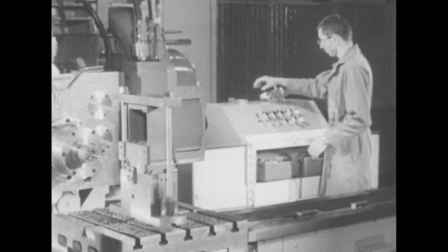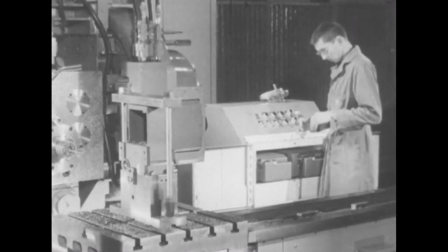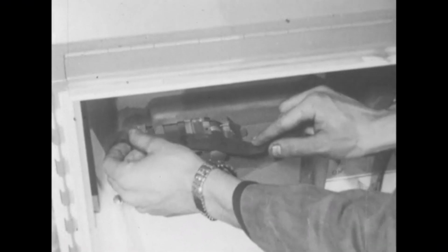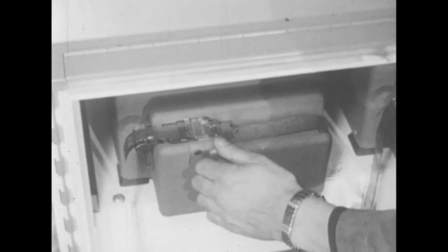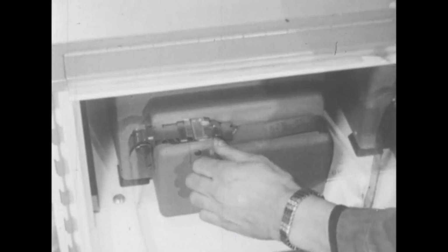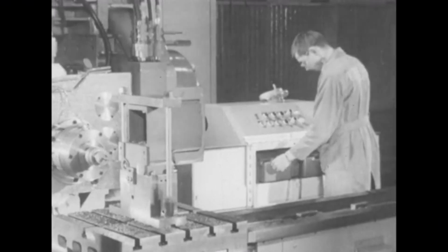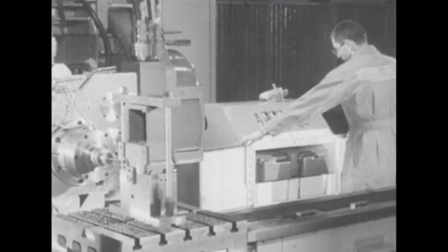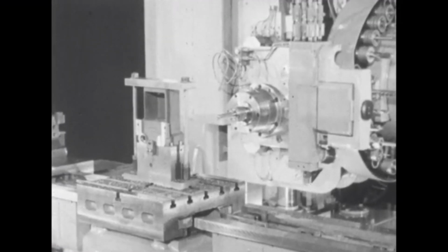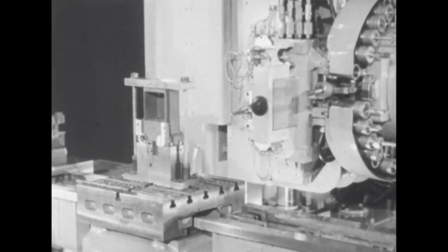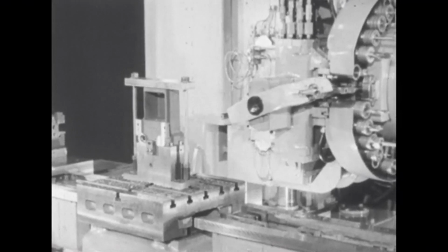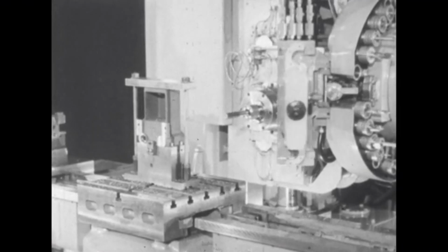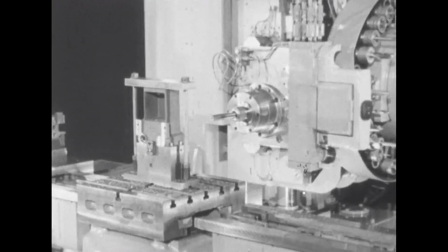Upon completion of the setup work, the labor cost of machining each part using the Milwaukee-Matic concept is considerably less than that of conventional methods. Furthermore, because the cycle repeats itself exactly for any number of units produced, the hazard of human error is virtually eliminated, with resulting lower scrap rates. In cases where repetitive orders are involved, all that is needed for the next lot is to reinsert the previously used tape, mount the required tools in the storage magazine, and furnish material.